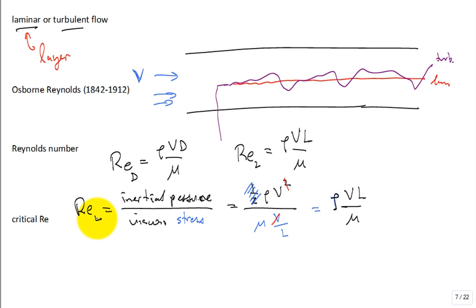So the Reynolds number, don't forget it. It's probably on your FE exam. Multiple choice question: Reynolds number can be interpreted as a ratio of gravitational to viscous, buoyancy to inertial, inertial to viscous, and then you have your 5 choices, and in there will be something like inertial to viscous forces. True? True. The critical Reynolds number for when you see the difference between laminar and turbulent flow in a pipe is around 2300.